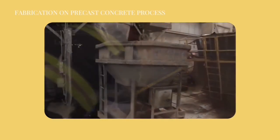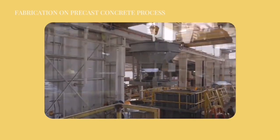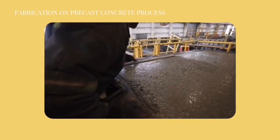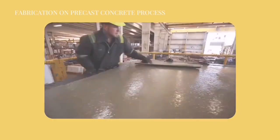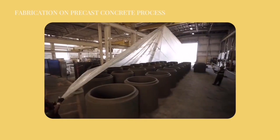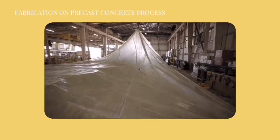The approved batch is transported in a bucket via an overhead crane to the product form on the production floor. Concrete is placed into the form from one location, and care is taken to allow the concrete to float without entrapping air voids. Once the form is filled, the top of the form is screeded off and the specified finish is applied. Once the concrete is placed, the curing process begins. This may include tarping the product overnight in order to capture the heat from the hydration process. The controlled environment of a precast factory enables the product to properly cure and reach the full design strength.